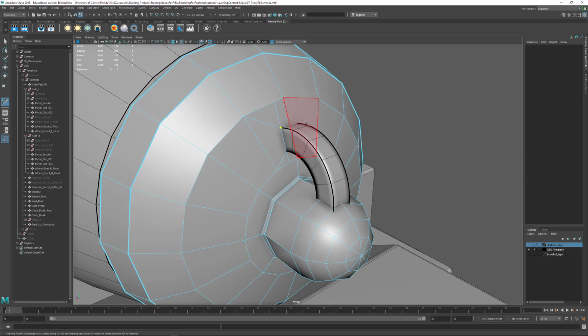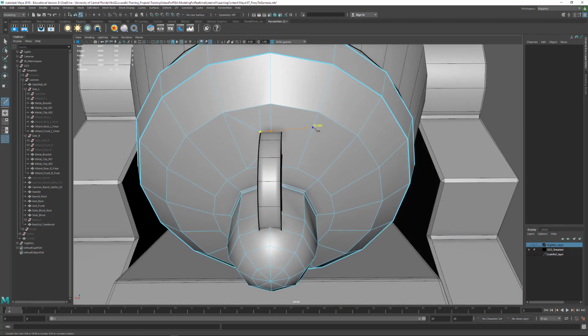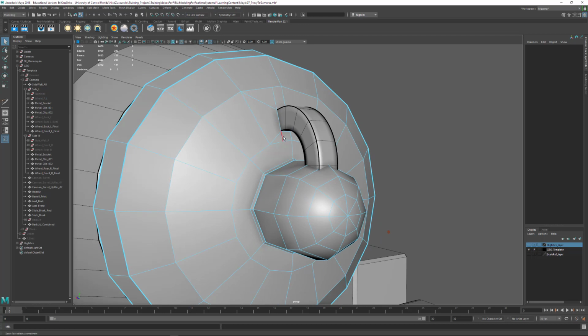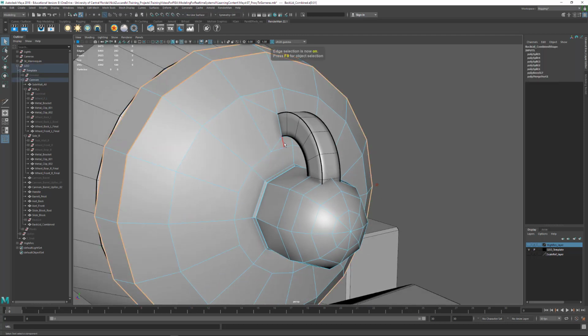I'll take this and we'll go straight across holding down Control and Shift. I'll hit enter. That'll make a straight line going across. I'll go drag from here and hold down Control and Shift, and I'll make a straight line going here. I'll tap Q to go over that tool, F10. I'm going to select this edge, hit F9, get rid of these extra verts that we got here.